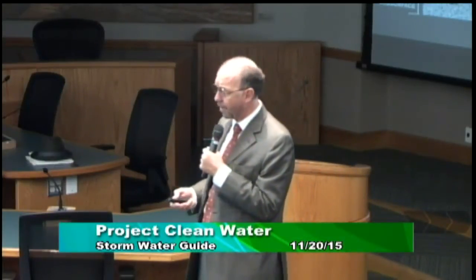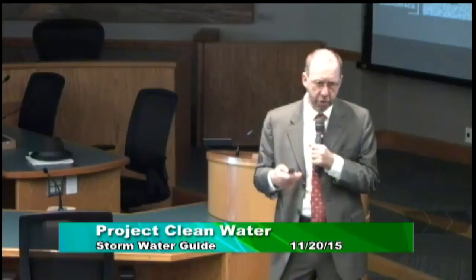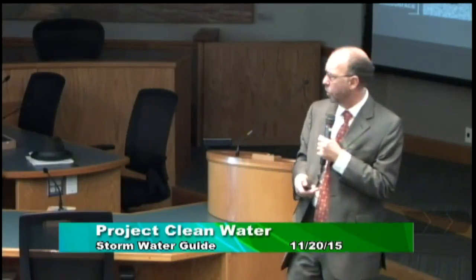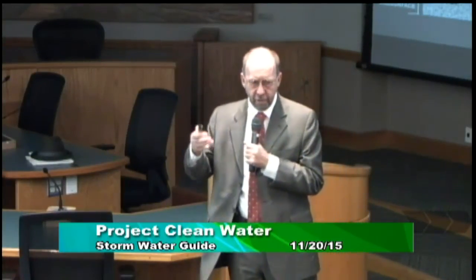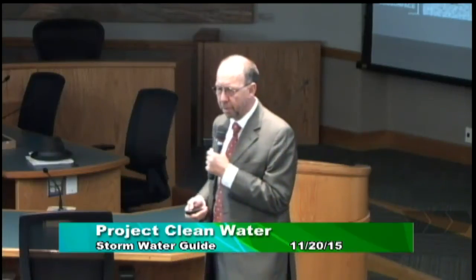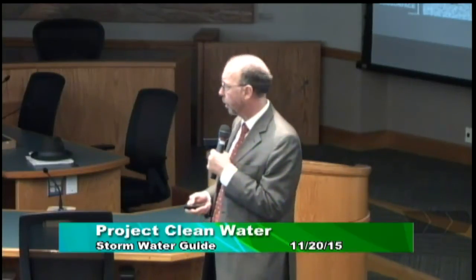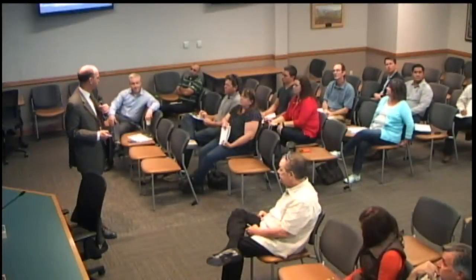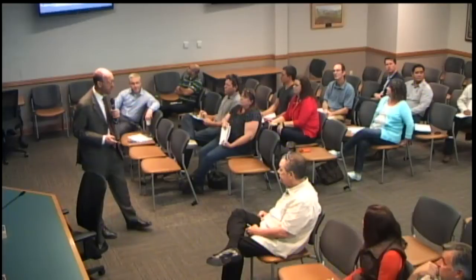If you could go for an average depth up to 18 inches, you can specify it either as a depth or a volume and take credit for that because of the effect of being able to back up into it during the big storms. So we hope this will help ease the problem of having to dig excavations so deep or to use so much site area in order to comply with PCRs using bioretention.